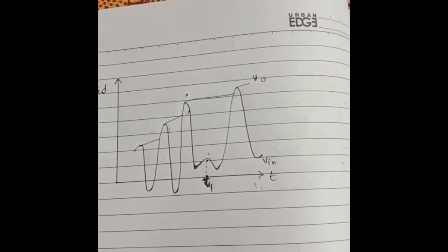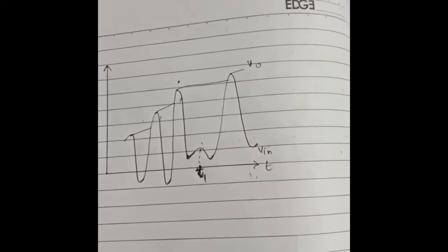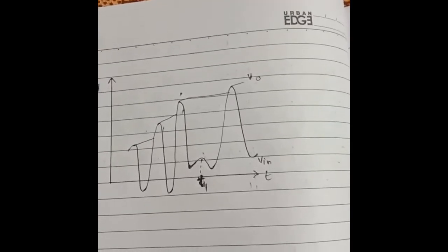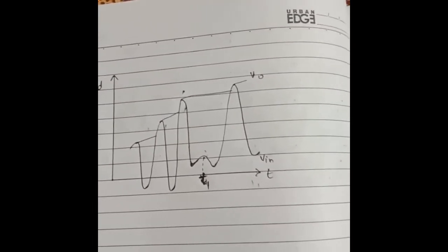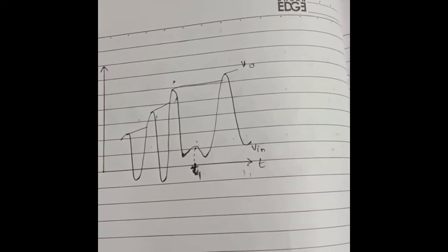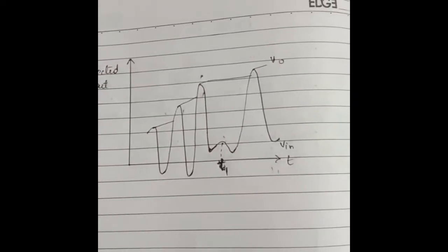As it is a positive peak detector, one can also construct a negative peak detector circuit that will hold the lowest or most negative signal voltage. This is basically done by reversing the polarity of the diode in the circuit.